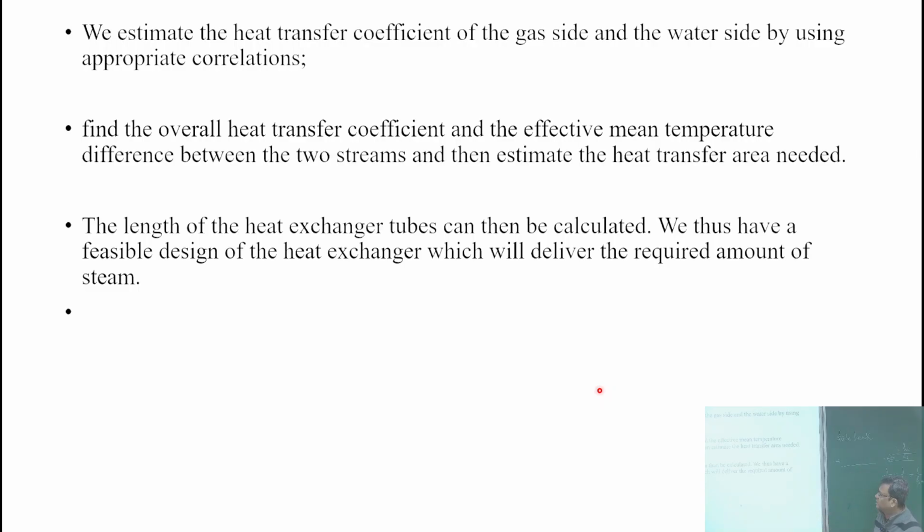And once you have all the temperatures, then you can also calculate some mean temperature difference, isn't it? Like LMTD, you must have studied, log mean temperature difference, but here calculations will be a little bit different because of the complicated geometry that we have. Okay, and so we got an effective mean temperature difference between the two streams.